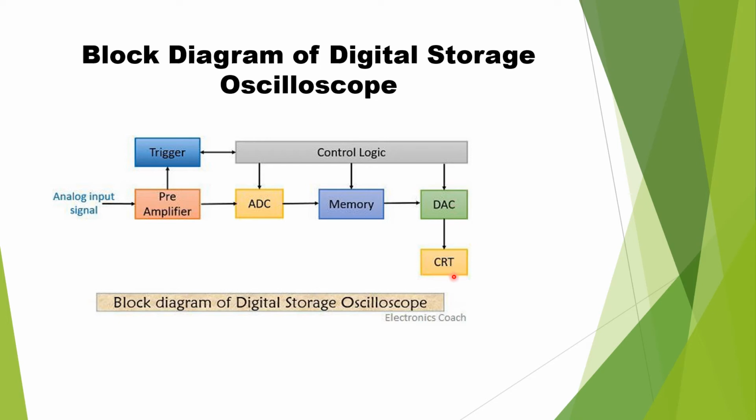Any further changes in the input will re-trigger the oscilloscope, which causes the memory to be reset. That means the memory is overwritten with the new incoming data unless the system is in hold mode. By the application of hold mode, the signal traces can be analyzed by the user according to the user's choice.